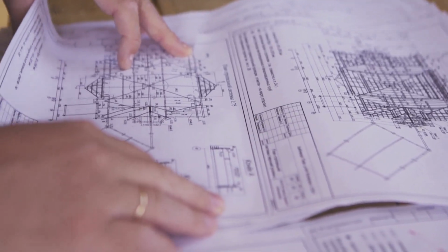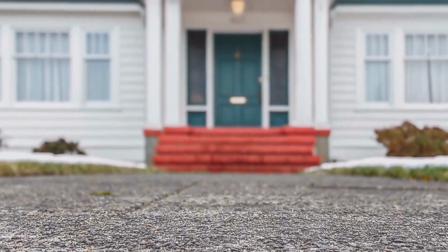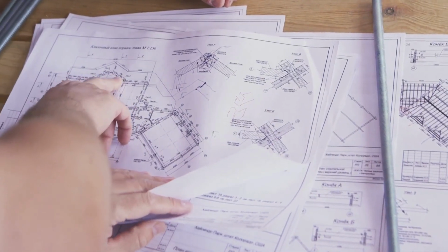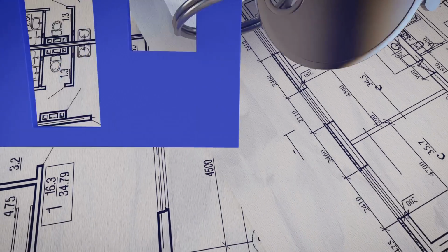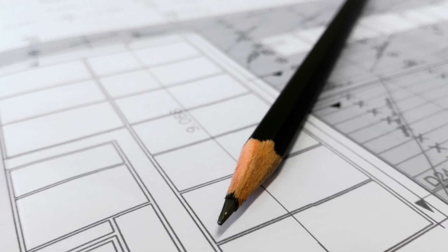Section 6. Practical example. Putting it all together. Let's look at a simple example. Imagine a blueprint for a straight sidewalk leading to your front door. The dimensions show it's 4 feet wide and 30 feet long. The thickness is marked as 4 inches. The slope is indicated as 2%, sloping away from the house.